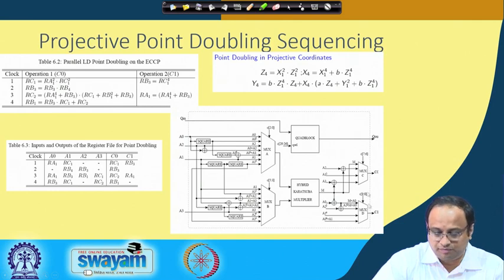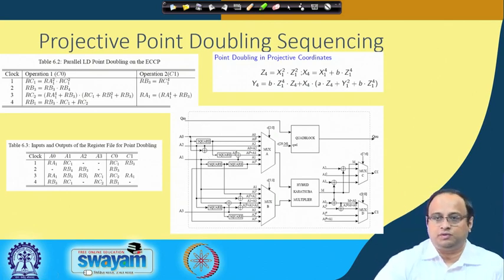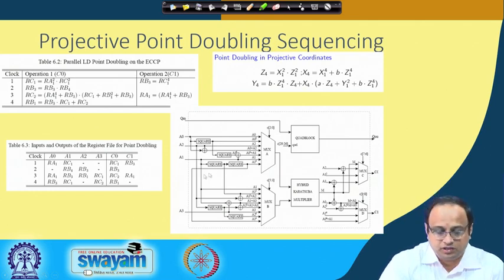But at the same time, in my data path there are some other peripheral circuits like addition and squaring, and when 2 squarings are successive, you can also raise an element to a power of 4. These kinds of computations are kept so that you can do them independent of the multiplier, and they are also less costly. So you can provide dedicated support for them. You have to plan this entire circuit.